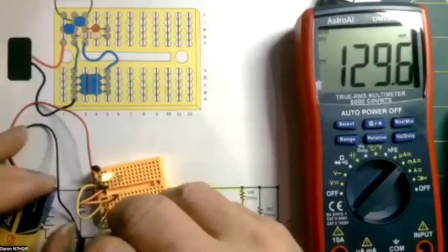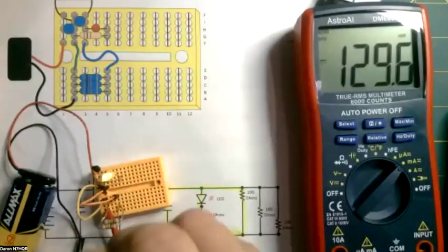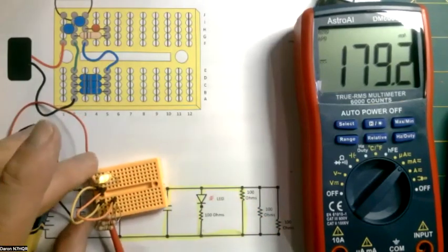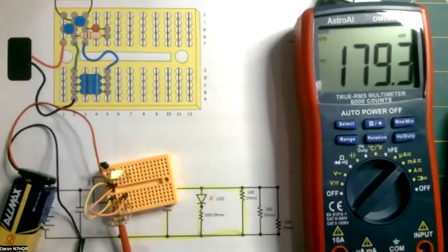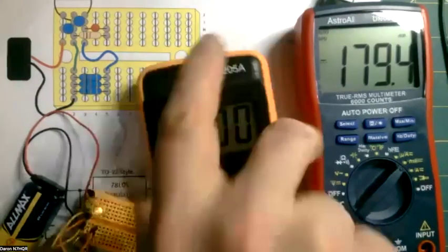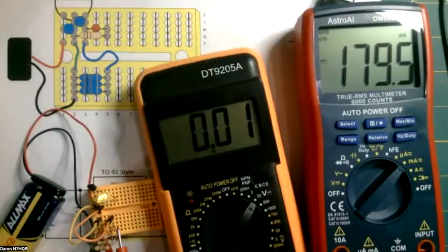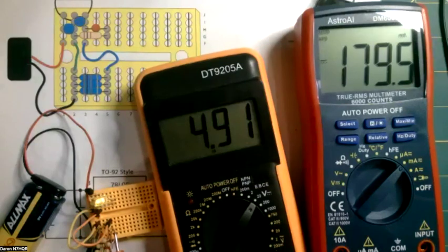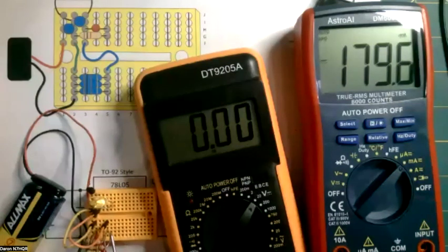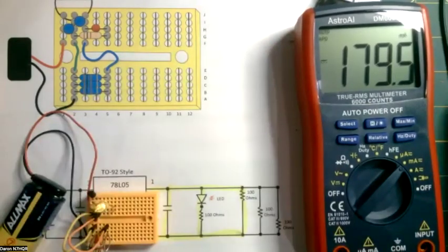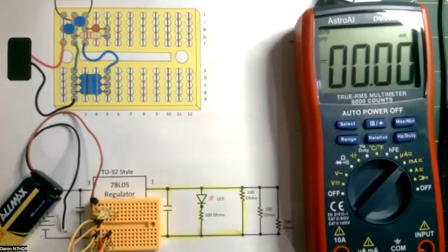All right. Now, I've done this and it hasn't smoked it yet, but it's definitely a thermal issue on the thing, so okay, now, 180 milliamps. Yeah, it's warming up. Okay, quickly measure the voltage. Oh, sorry. Oh, it's still at 5 volts. It's only dropped 1/10 of a volt. With mine, it dropped a full 1/10 of a volt. Okay, go ahead and turn it off so we don't burn it up.